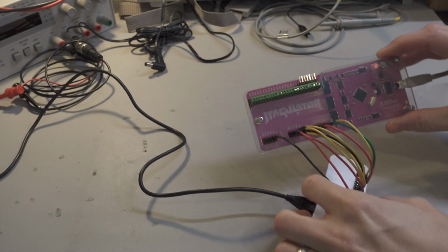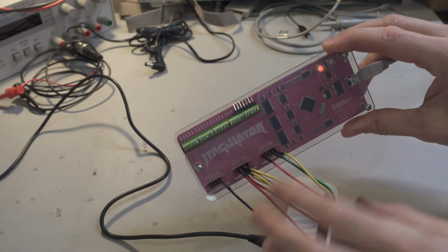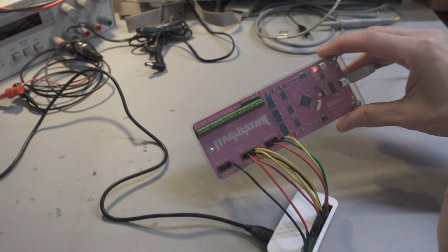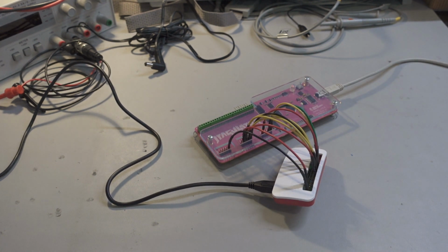When we're in a secondary mode, the LED indicator is solid red. So if you end up using this mode and forgetting to exit that mode before you put the thing away, a week later you might come out, plug your JTAGulator back in, and it's going to be a red light, and it's not going to be responsive to terminal program input. You're going to be like, what's going on? Hit Control X, that's going to bring you back.